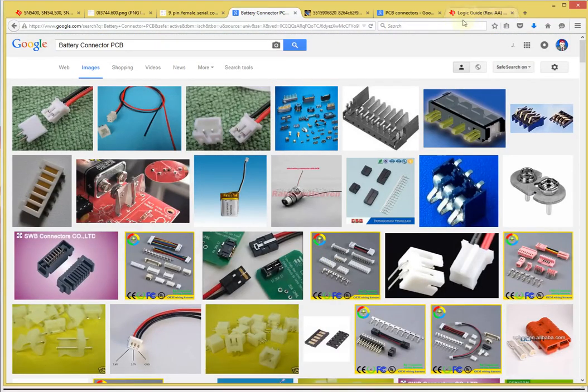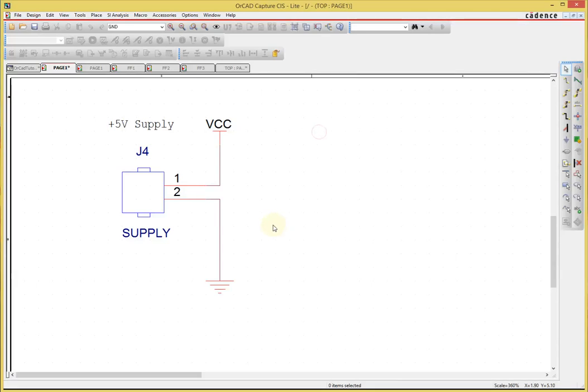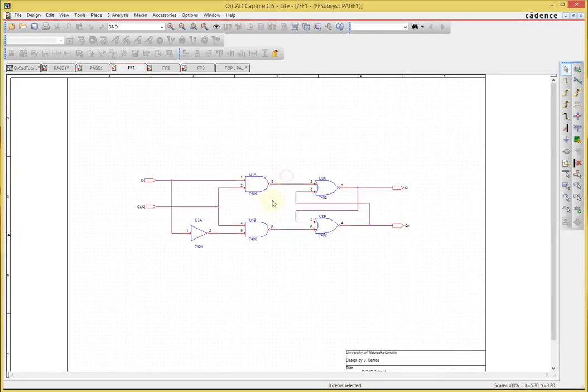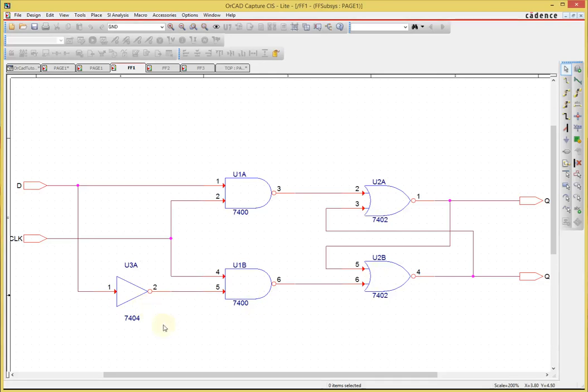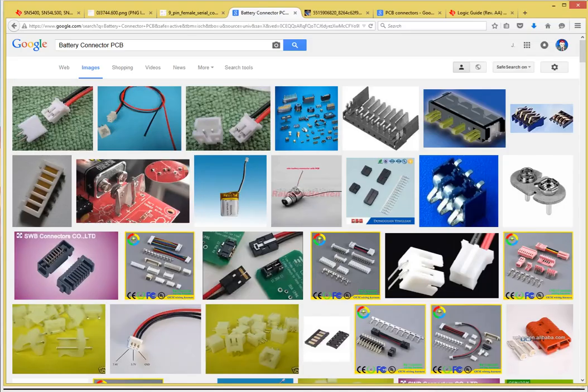Let's talk about logic parts. Let's go back to our schematic, back up, and descend into one of these. We have 3 unique types of logic devices, and these are all 14-pin DIPs. I want to use 14-pin DIPs, and I use generic parts: 7400, 7400, 7402. I did this for the purpose of this tutorial, but when you're doing research, the part number is not going to be this simple, because the manufacturers provide a variety of logic families and different part categories.